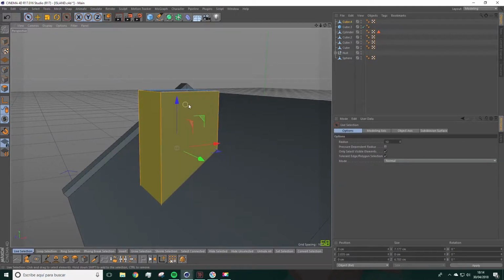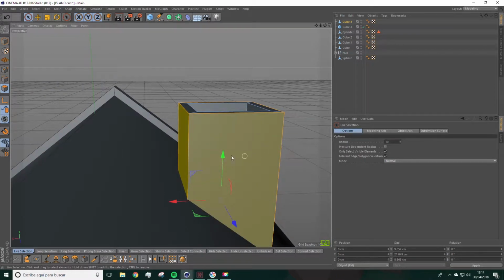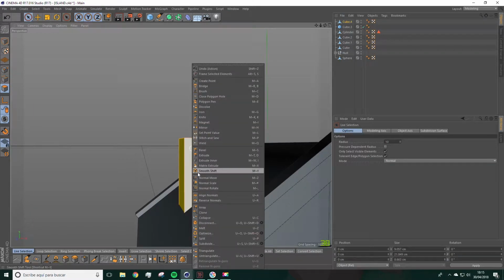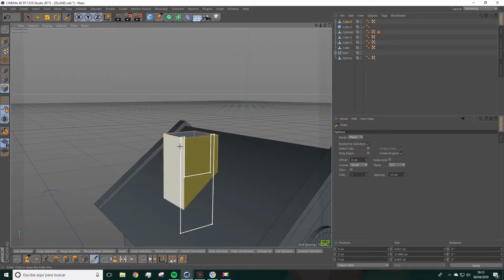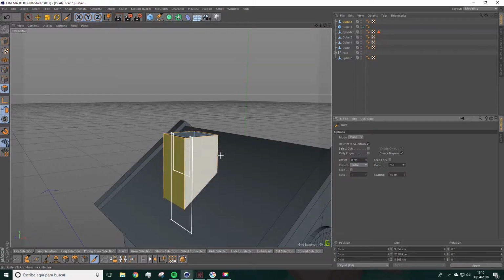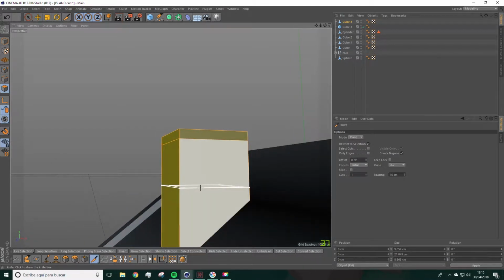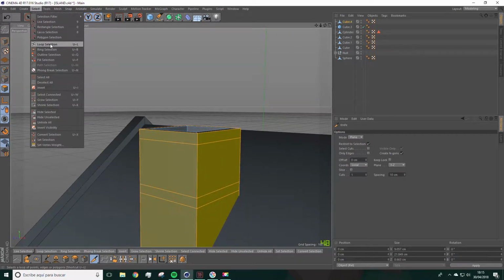Great. In order to generate more geometric shapes, we are going to insert some cuts. So, to do so, right-click and click on knife to make a cut. Over here, more or less. Although we need to change the plane. So go here to the Options panel and change it to Plane XZ. So as I said, insert one cut here and another here, and that's it.